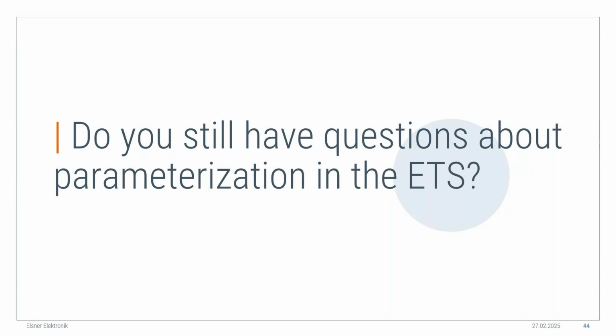For example, if HVAC priority 1 is connected to a window contact that says window is open, don't heat right now, and HVAC priority 2 is a timer that says start the heating every morning at 8 a.m., and the window is open, then HVAC priority 1 will be fulfilled and HVAC priority 2 won't be fulfilled. I hope that makes sense.